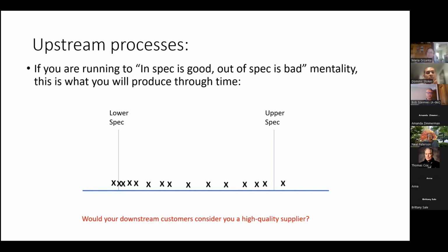That's absolutely 100% correct, what you and he said. Control limits are completely different than spec limits. Control limits come from the natural variability in your process, which could care less about what your specs are. It's got built-in variability, comes from that. Those x's are usually x bars. You're usually taking a sample of 5 or 10 or something, so you're plotting averages, not individual parts, but that's a whole other discussion.